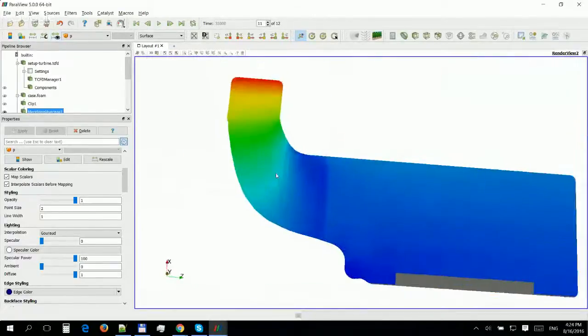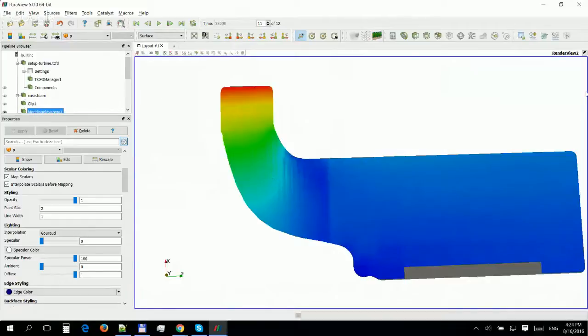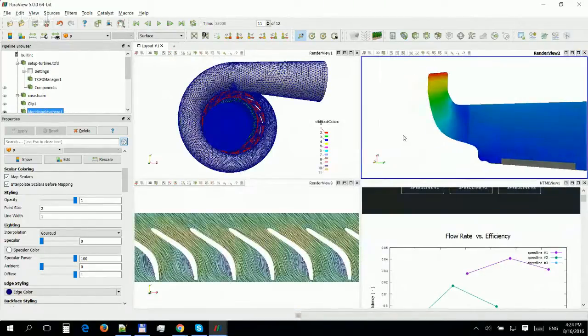Yeah. So then the very important thing, of course, is to see your results, to make some visual post-processing of your results. For this we have created a special set of tools, which is called TurboBlade Post. It's part of Turbomachinery CFD, of course, and it helps you to compute, for example, the average of all your quantities in a meridional view. That's important. So maybe I can show you the meridian of the impeller and the outlet tube, and you can do the averages of all your quantities.